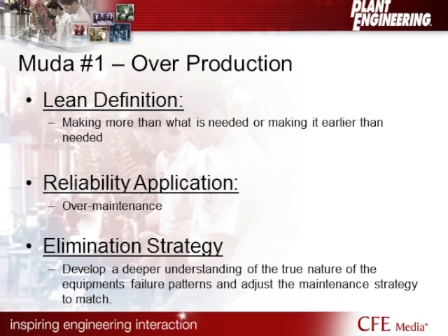And there are many issues that come with that. Not only is it the parts associated with doing too much maintenance, it's the invasive maintenance that you're doing that might bring in infant mortality. It's also the fact that you're having to take that equipment out of service to do that maintenance. So there's a lot of waste associated with this idea of maintenance overproduction.